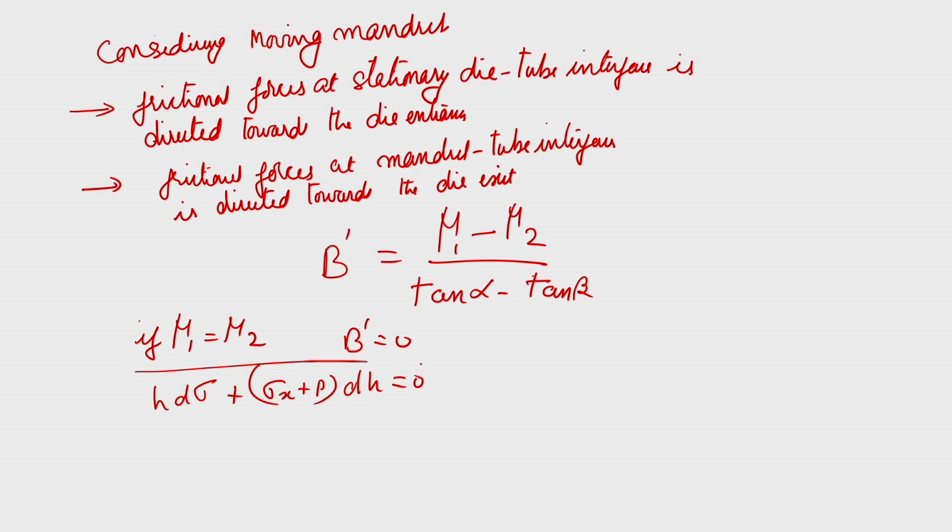So, if you are able to have this frictional coefficient the same, then redundant deformation and friction and those factors will be nullified. So, you will need only a lower stress which is equal to your homogeneous deformation.